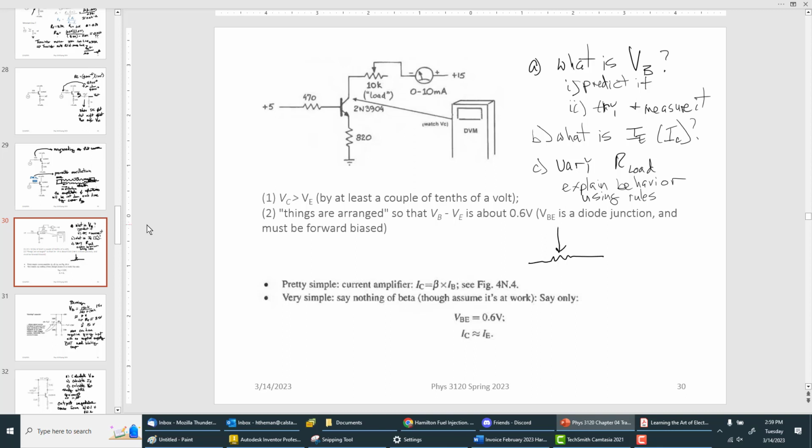I'll tell you that when you look at the little resistor that you're going to get, it's a 3-terminal device. It's got a blue square with a white knob, and you put a screwdriver into it to turn it around. And so the two outer terminals, these 1 and 2, are the outer terminals. And then number 3 is the middle terminal, and that's the variable one. So when you use this, notice the way they have it hooked up here. They're using terminals 1 and 3. So you're using 1 and 3 or 2 and 3.